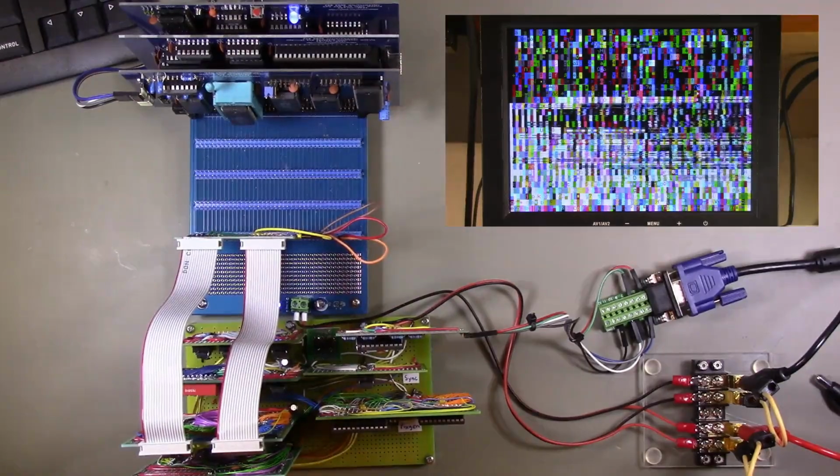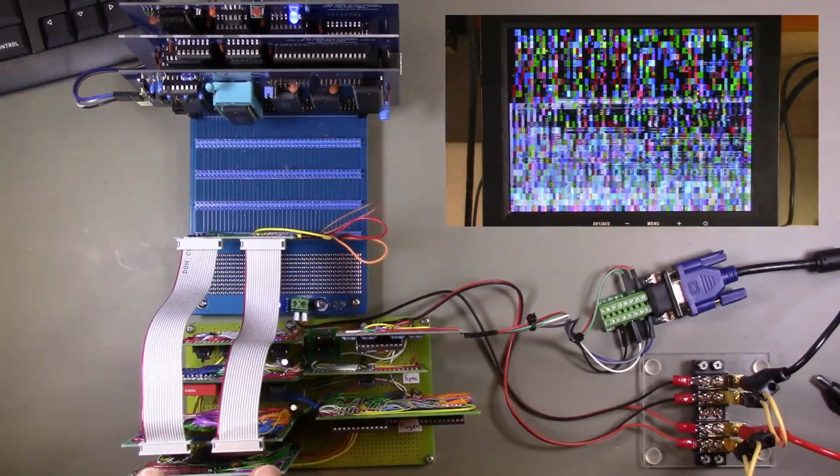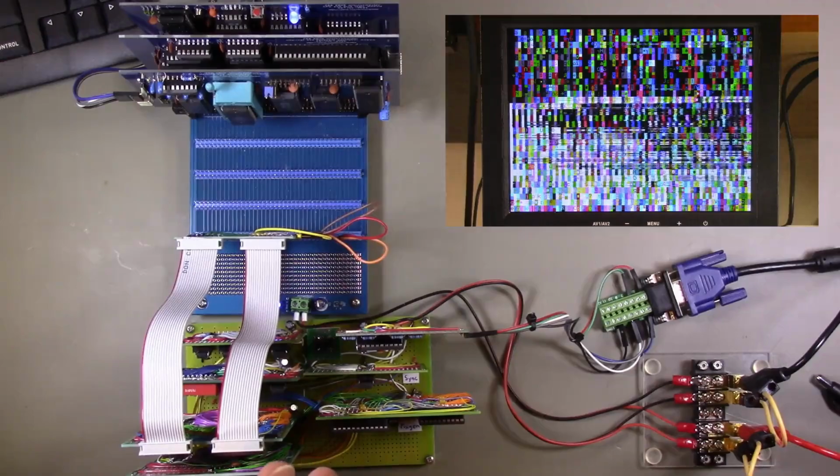So here is my sort of very ad hoc analysis. I think the problem is that this readout module has some long wires, it has no ground plane, it's kind of a worst case scenario for signal integrity. So I think what we potentially need to use is parts that aren't as prone to creating these voltage spikes.